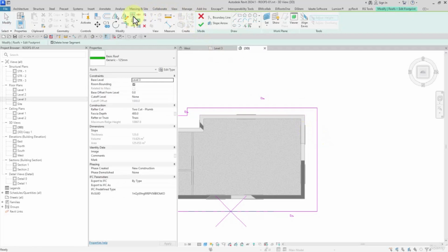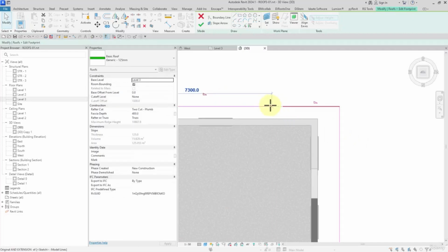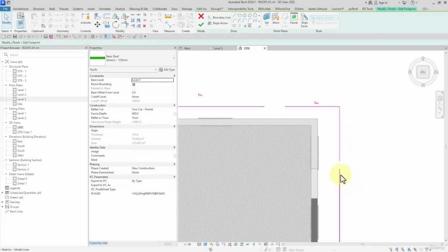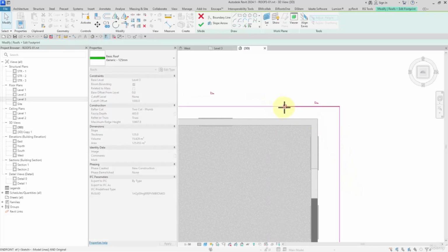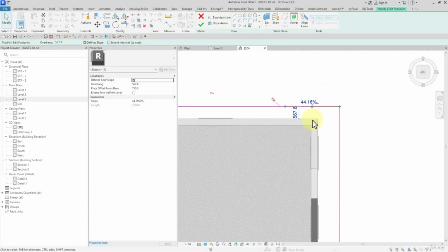And then at the other side, a split. I uncheck delete, and I can define a specific value for deleting or splitting them, 25 hundredths and 2500 at the other side. Then I connect them, then I uncheck define slope, cancel.